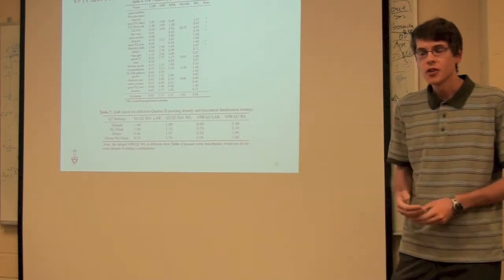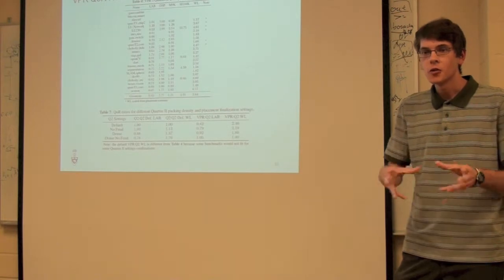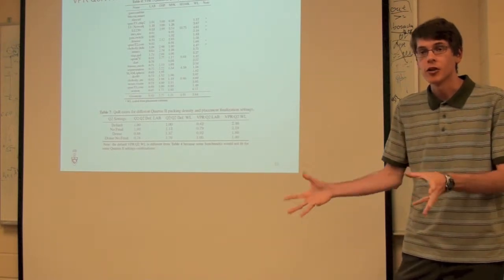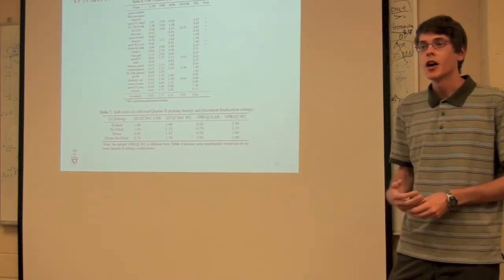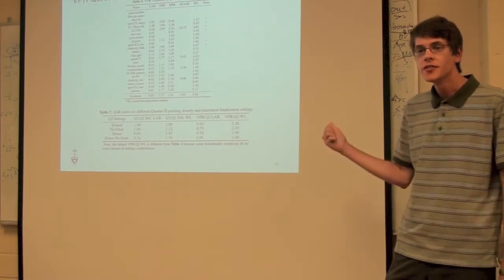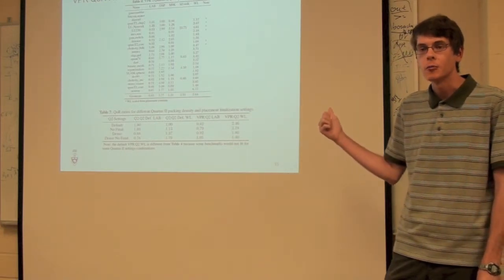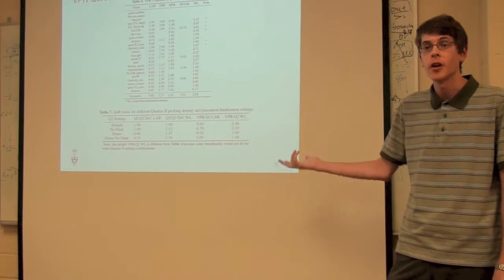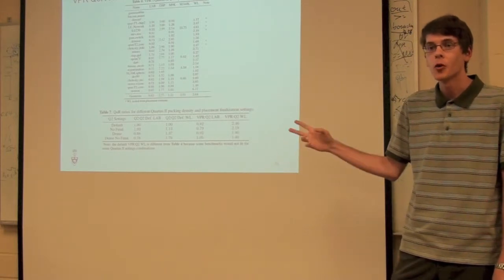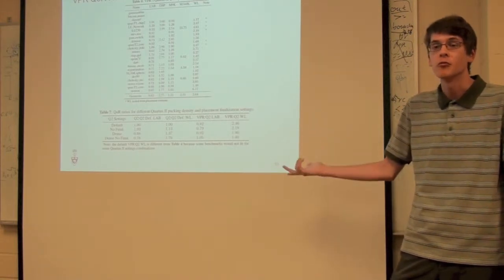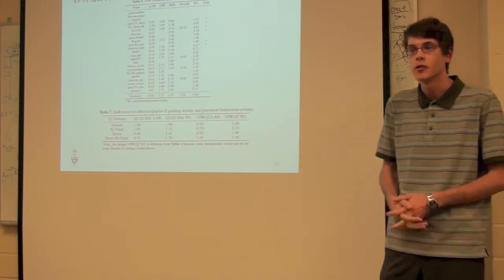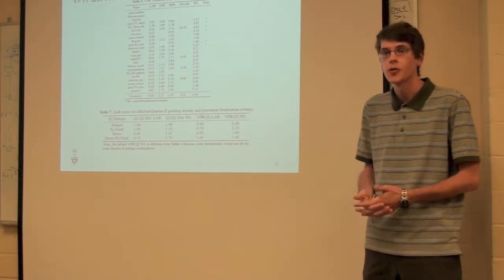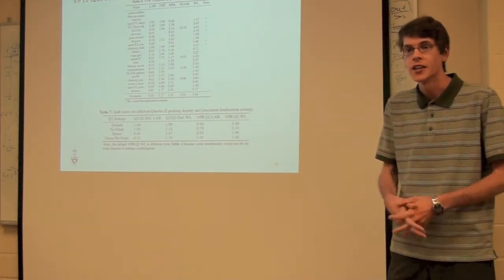That's possible. However, there's also another aspect to wire length, which is how routable your design is. Okay, yeah, that's the part I forgot about. So we did see that on 3 of the benchmarks, VPR was able to pack and place but not find a routing solution. So part of the reason could be that we have more wire length than Quartus is using because of the dense packing.